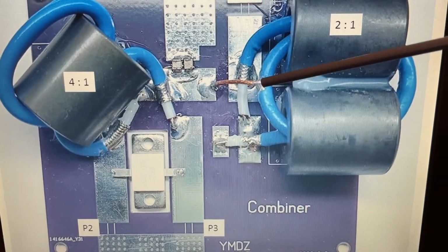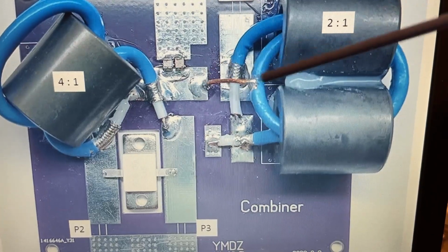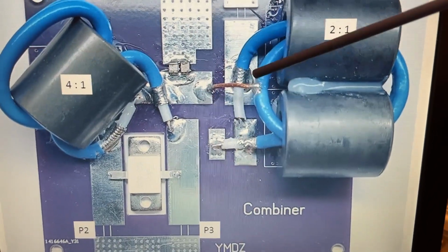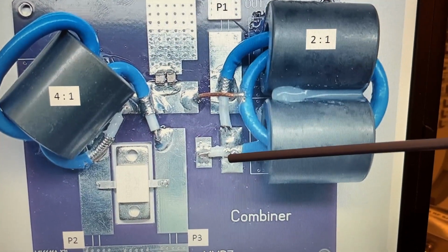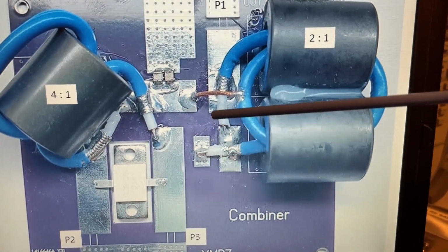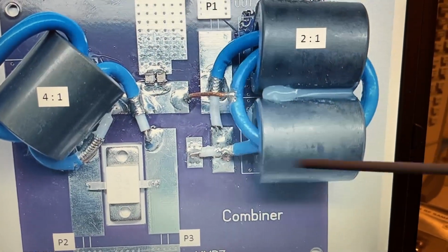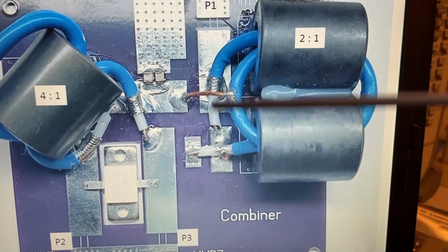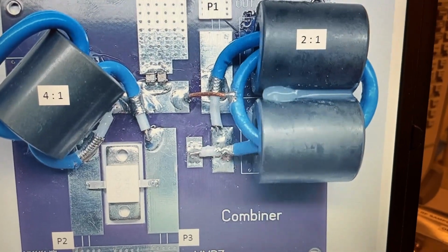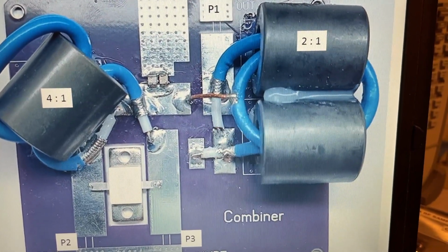And then what do you see? You see a jumper wire. This is the center tap on the schematic, right? Then we have our 2nd turn, and that's connected to the center conductor. And then we have 2 turns of the center conductor, which goes to ground. So these 2 windings are just in series. It's that simple, and that's what makes it an auto transformer.